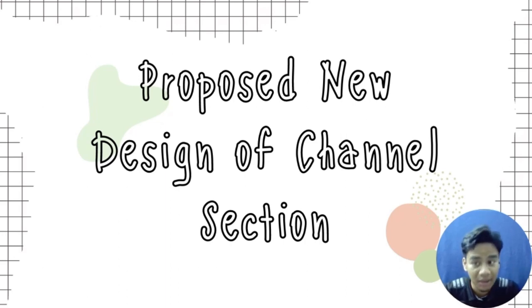I will present about the proposed new design of channel section. Based on the calculated and analyzed data, the cause of flash flood in the area is the small area of the channel and it is too shallow. Therefore, to prevent the flash flood from occurring continuously, the channel can be enlarged and deepened, so it can raise the flow of the water to more than the peak of flow, which is 13.219 meters cubed per second.